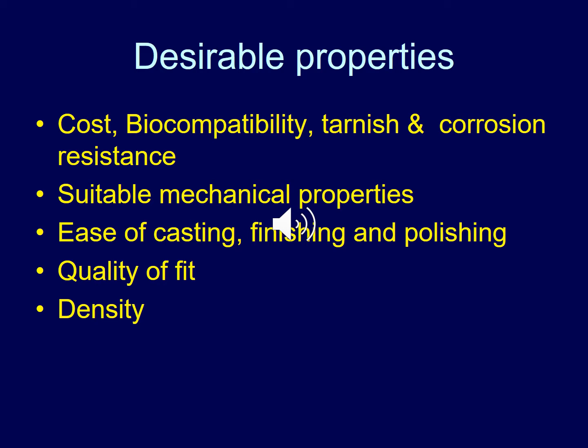Suitability for a specific application, be it a low-stress bearing inlay or a posterior bridge, is determined primarily by the mechanical properties of the alloy, such as its stiffness, strength, ductility, and hardness. Stiffness is a consequence both of design and of the elastic modulus of the alloy. The higher the elastic modulus, the stiffer the structure will be for the same shape. This is an important consideration, especially for long-span bridges, cast posts, partial dentures, and denture clasps.